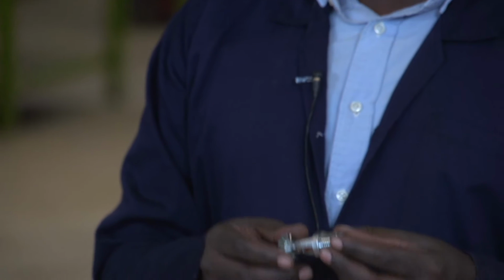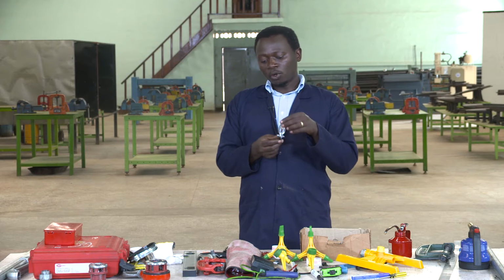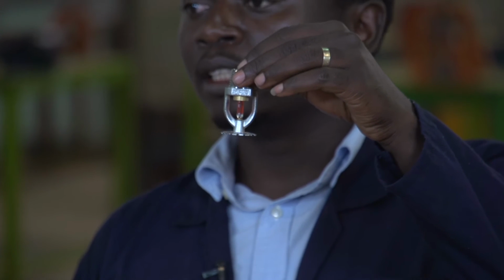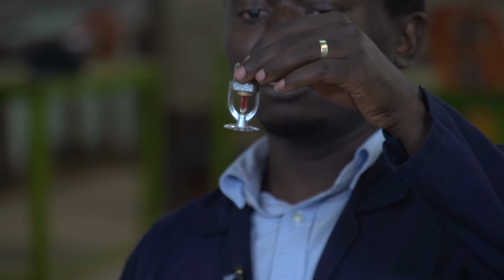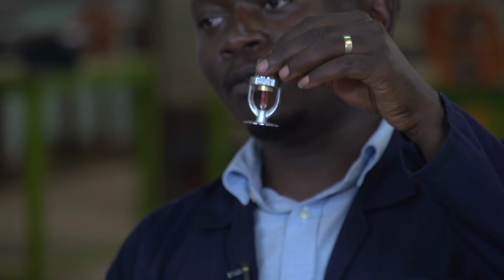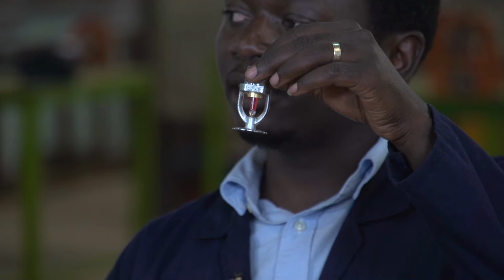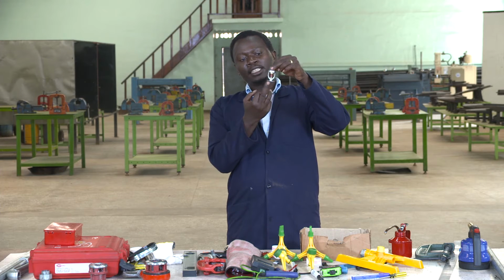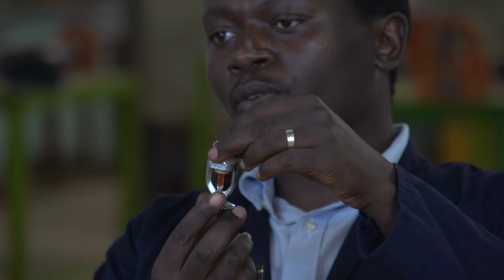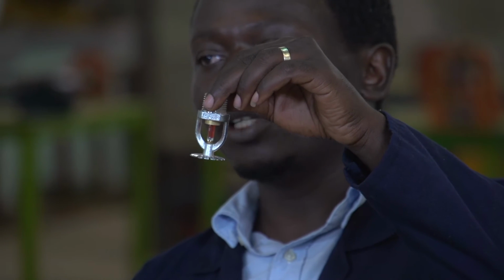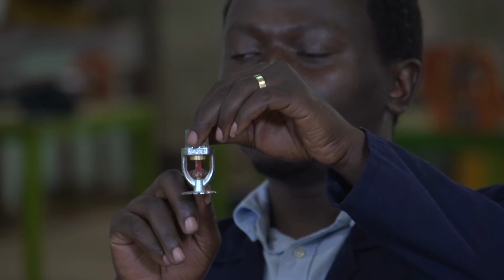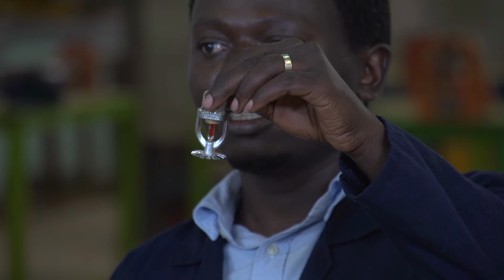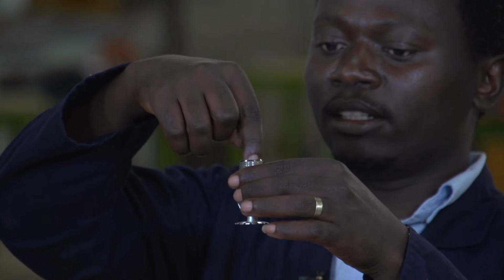So for the first stage, it cannot break by itself when it is hanging on the pipe. The factor that breaks these kinds of sprinklers is fire, or it has to be heat. If the heat is coming, this metal will absorb the temperature or heat, and it will melt or cause the liquid inside the bubble to expand, and it breaks. Then the pressure which is here will push